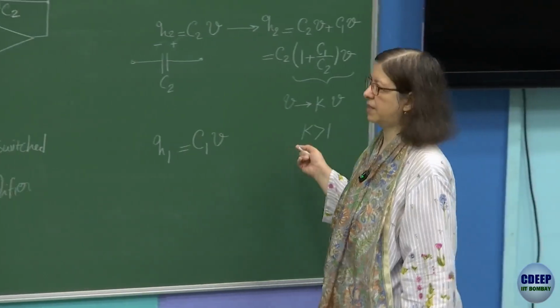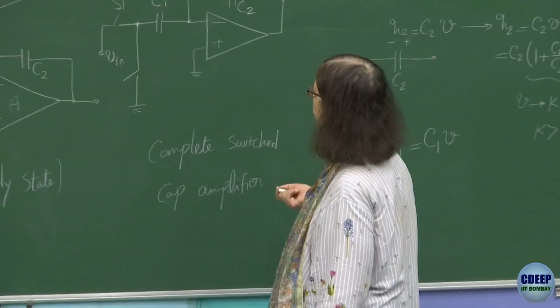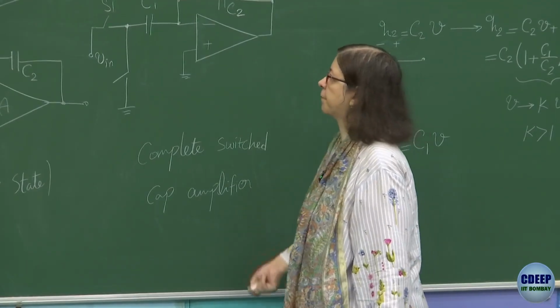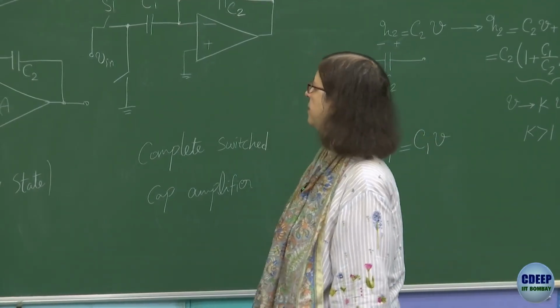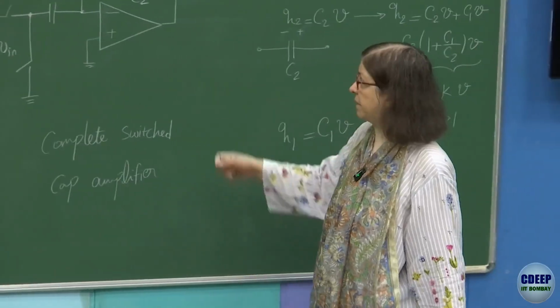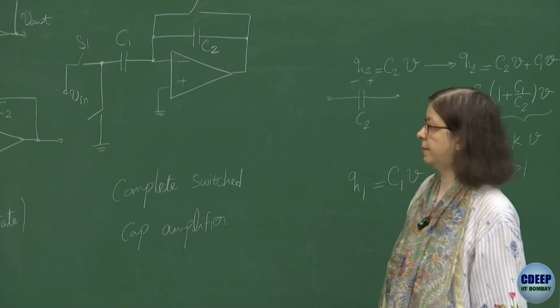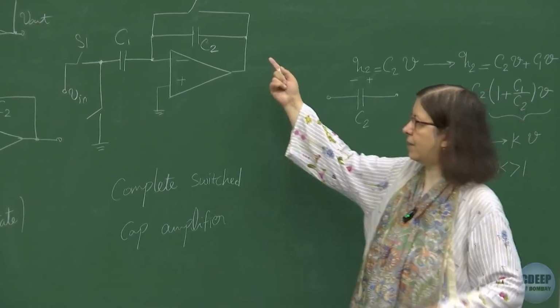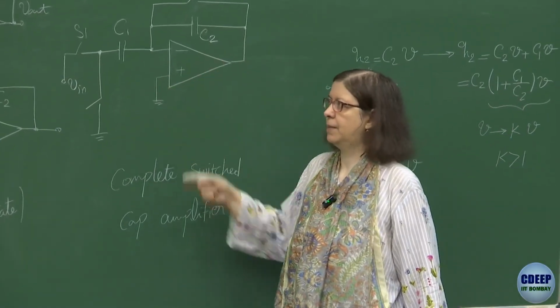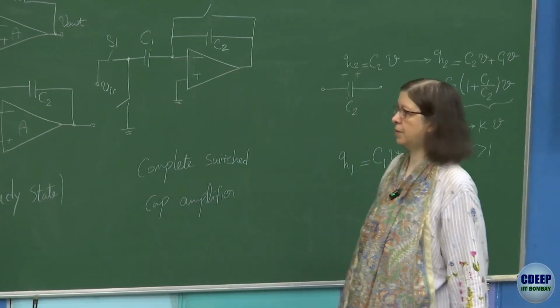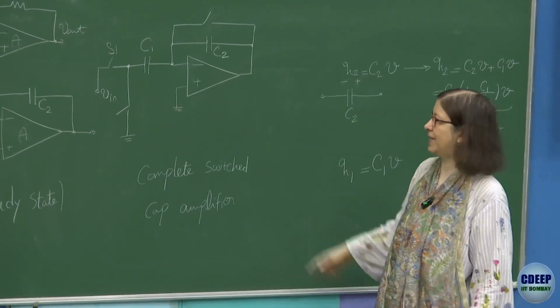So that's the whole concept actually behind this switching. In fact, here, exactly the same thing is being done. Okay. And in fact, if you keep them exactly equal, then actually gain will be 1. In fact, we can also make a unity gain transfer function in discrete time using this configuration rather than the other configuration. But this needs 2 capacitors.